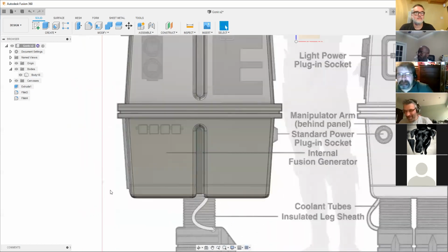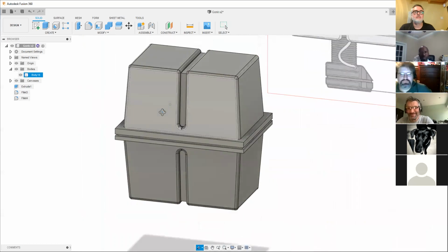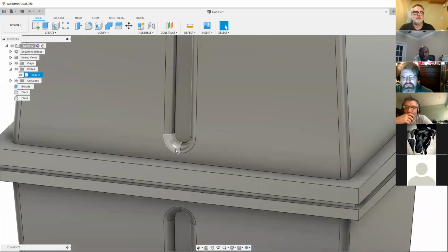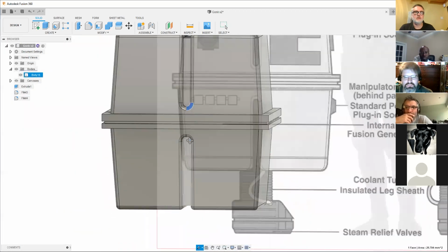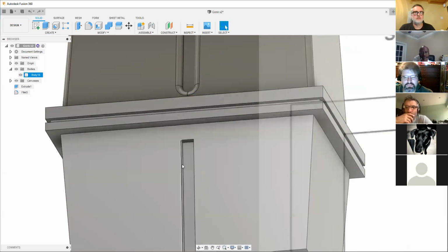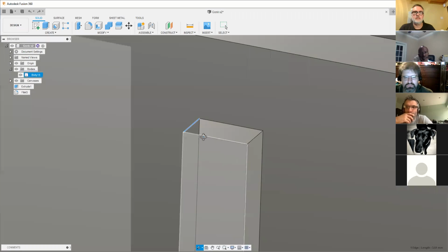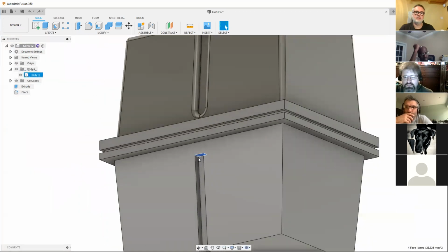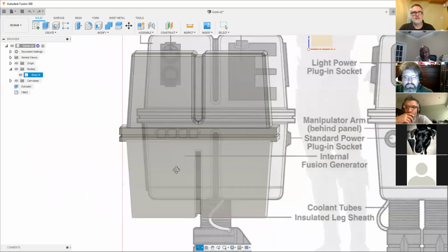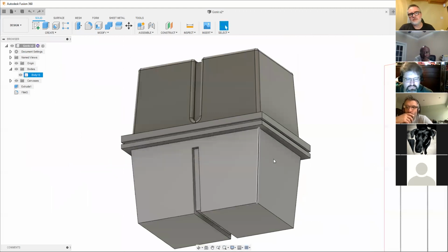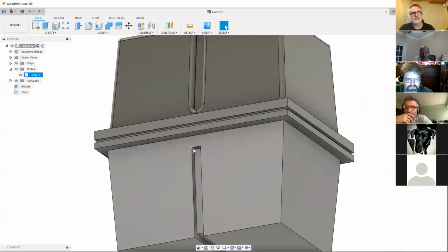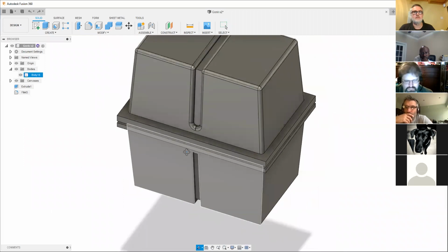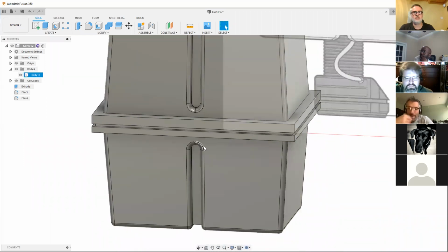So Mike, I'm getting the rounded edges on the box. How are you getting the curve at the bottom of the inset? Yeah, there. So if I just undo, that's selecting these 2 inner lines here. Oh, okay, that makes sense. That's the one I missed. So you may miss lines. The problem is if you then try and fillet lines afterwards, it gets a bit complicated because it's trying to fillet on top of existing filleted lines. So you really want to do all the fillets in one go. That's where that comes from.